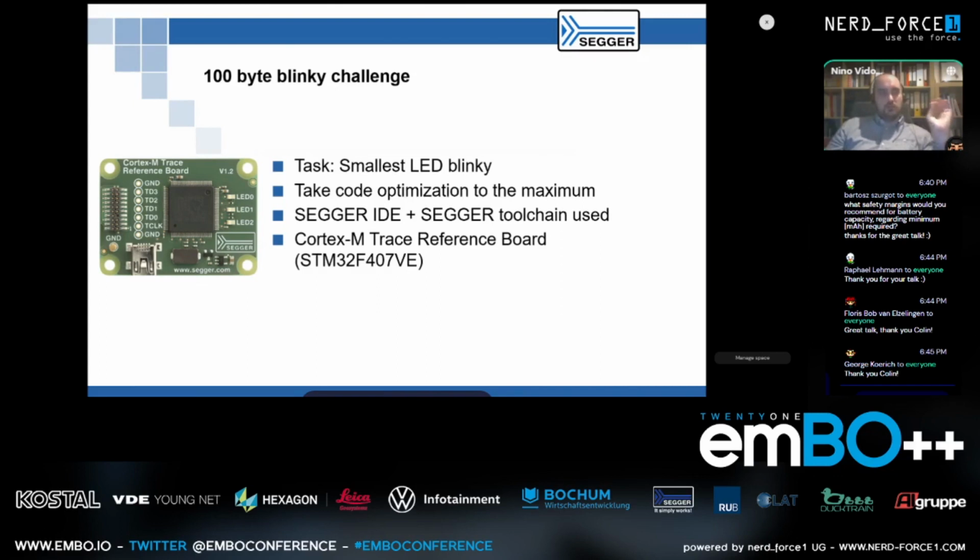So we took a look at exactly what's the minimum you need to get such a target device up and running to still have workable code. We really went to the max there. This would maybe not be exactly a real world scenario because we threw out the whole interrupt handler. We essentially limited the initialization to have only the things initialized to just get this LED blinking, and the end result was really impressive, and it was less than 100 bytes. I think it was 97 or 98 bytes.